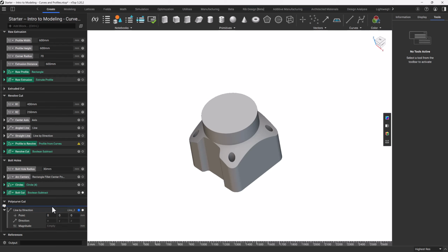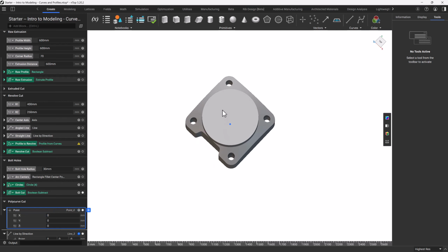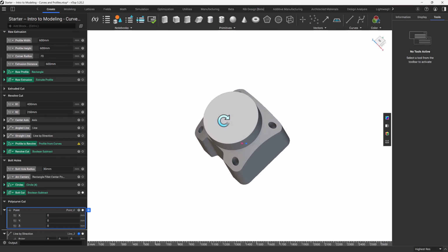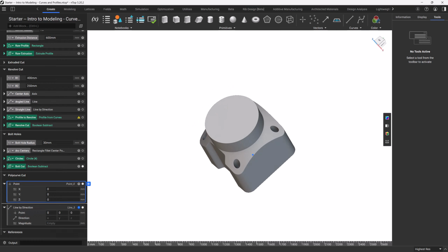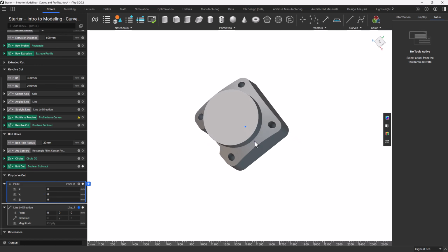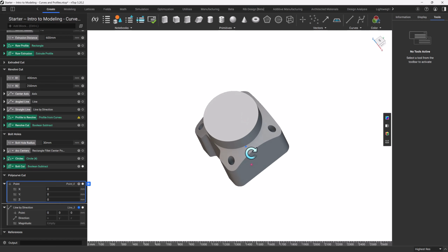For our start point then, I'll load in a point block. And for our X location, if I look from the top, I just want that to be the centroid of our part. So our X location is actually just going to be 0, and I don't need to change that. For our Y though, I'm going to slightly offset this from the centroid of our part by the fillet radius, or the channel bend radius, excuse me, that we're going to use.